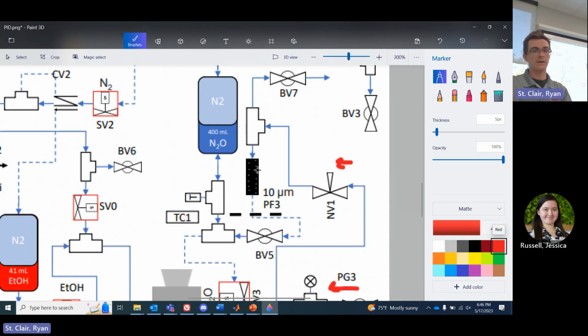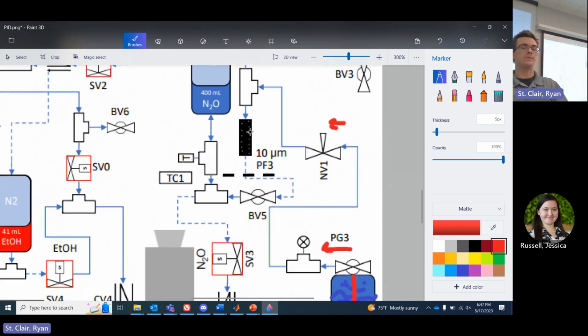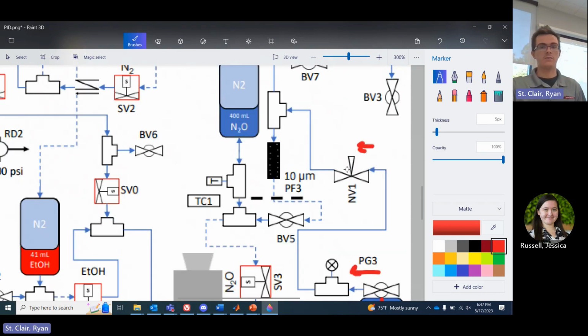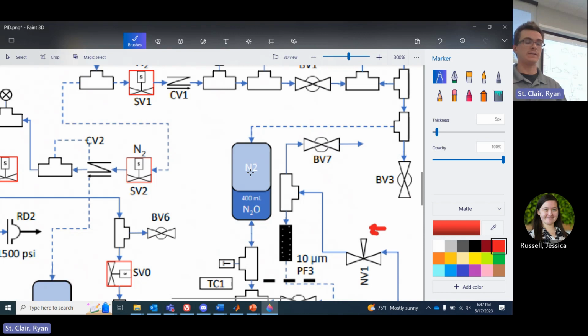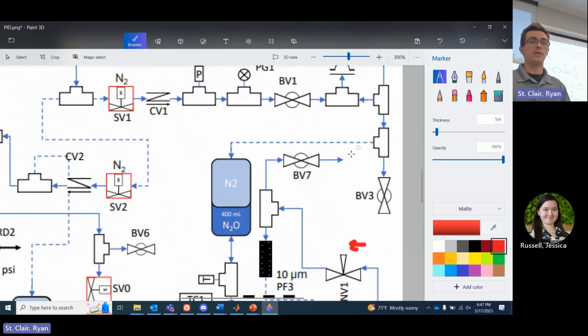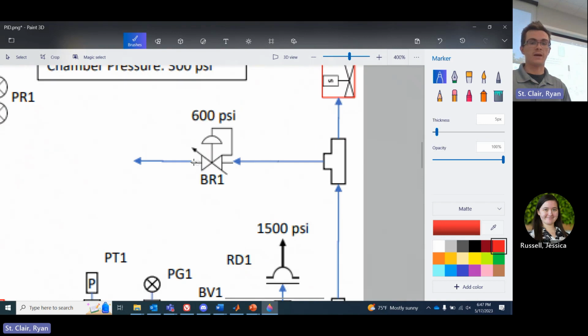And we have this T here, and it goes across this particulate filter again because we want to make sure there are no particulates entering our system in that high pressure oxidizer environment. And then it goes across this ball valve here. Basically now there's liquid nitrous oxide boiling off, getting the system cold, and it's at a high pressure. So you're constantly generating nitrous oxide gas in here, but that again is being let off by this back pressure regulator up here.